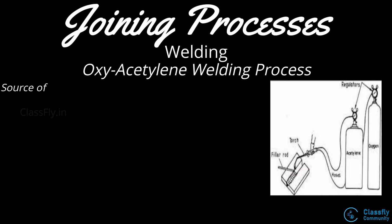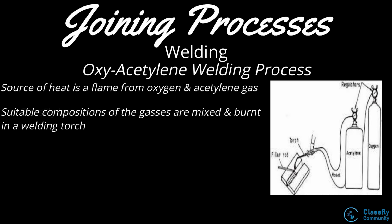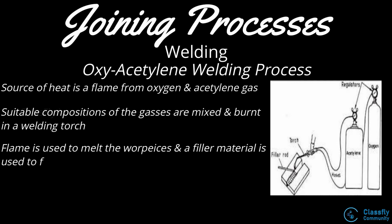Here, it uses the heat energy generated from a flame, which is produced by the mixture of oxygen and acetylene gas. Suitable compositions of both the gases are passed and mixed in a torch, and then undergo combustion, producing a flame which is used as the heat source in the welding process.